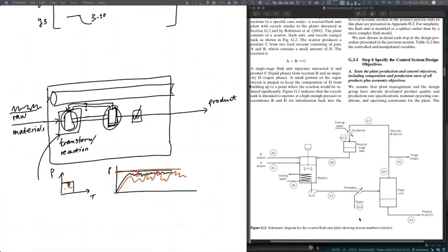So because that's a steady state, because the design was probably done with steady state assumptions, none of the vessels have any capacity, right? And so when you then try to size them, you use some rules of thumb, but you're very strongly motivated to reduce the capital cost of that plant. And so you put in a too small flash unit, too small pumps, the lines are undersized, the valves are undersized, and so on, because you're trying to minimize capital cost, and the control guy